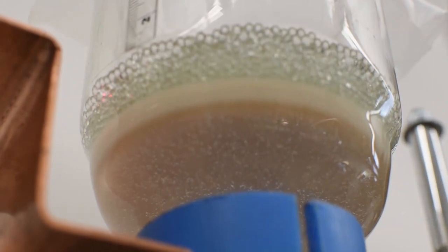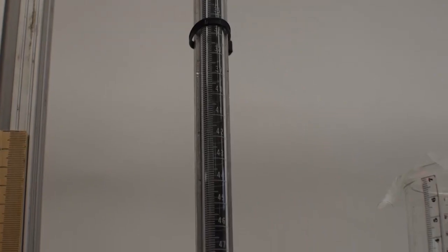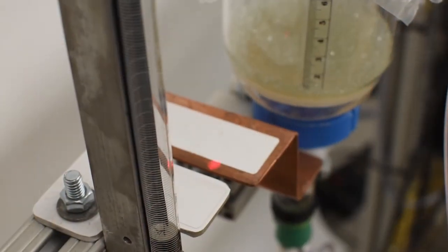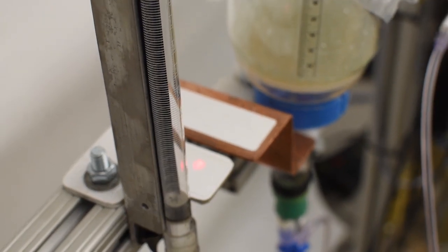The measurements initiate from the complete saturation condition, where the burette water level is at 0 and is parallel to the bottom of the sample. At the beginning of the automated measurements, the laser sensor collects two vertical positions, the Buchner funnel position and the burette position. The system waits for the equilibrium condition of the sample by monitoring the matric potential value. After reaching the equilibrium condition, the matric potential and the burette water volume are collected.